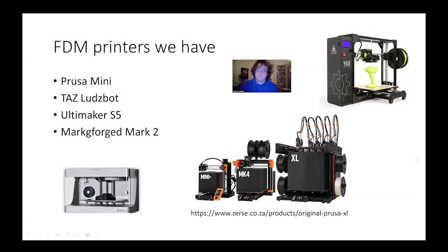Okay. Talking a little bit more about the XL, as you can see, it has multiple extruders, so you could do multiple colors and multiple materials. You could print in a support material that is different from what the main part is. Okay, so that's pretty nice with that one. And all of these are different extruders, so there's no purge cycle, which is helpful when you have a really long print with a lot of color changes.